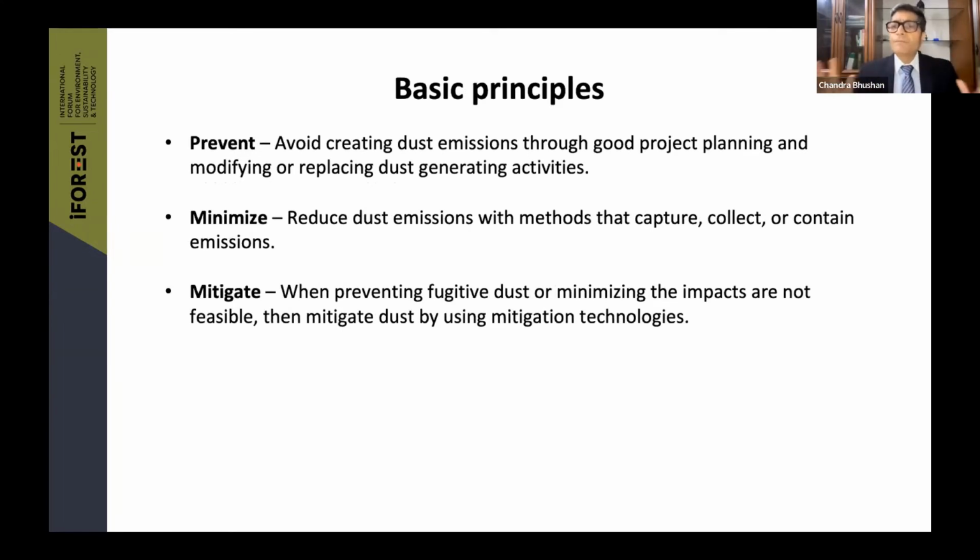So what are the basic principles of dust control? There are 3 principles. First is prevent, which means that you have to avoid creation of dust through good project planning. If you are doing a major infrastructure development project, then you must plan the project in such a way that you have the least amount of area which is open, which is generating dust.